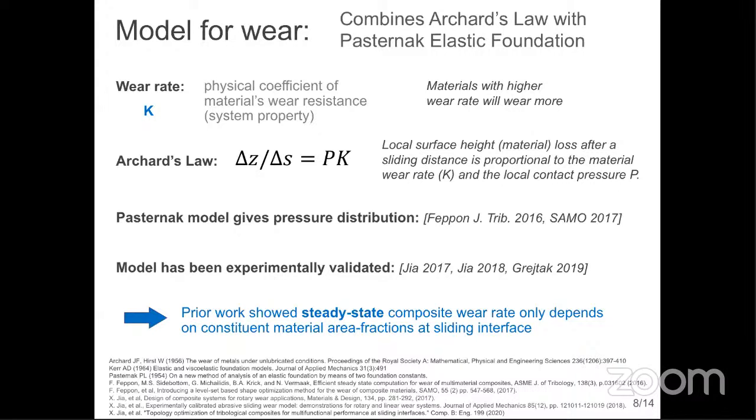Then we use the most common wear law, Archard's wear law, to get an expression for the local surface height as a function of sliding distance, local contact pressure, and wear rate. We then add Pasternak elastic foundation mechanics in order to get analytical solutions for the local contact pressure. Together, we get a well-posed parabolic PDE as a governing equation for wear.